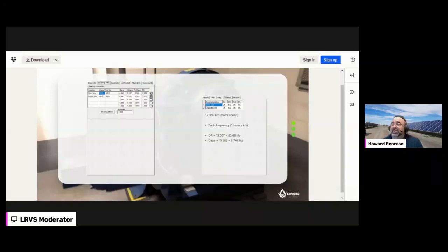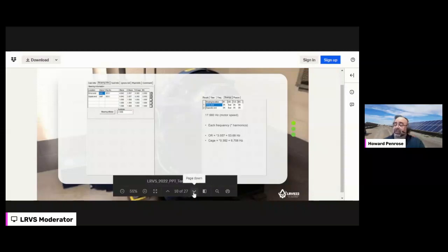And then also, as I take a look at it, these are the bearing multipliers. What's really nice for us doing this type of technology is that, other than the fact that everything happens in pairs instead of one times, the multipliers are the same. So a bearing defect shows up at the running speed times whatever the multiplier is, and usually can be detected rather early. When I show the last presentation, I'll show you how early it can be detected. But in this case, we'll see that there are some specific defects. Next slide, please.